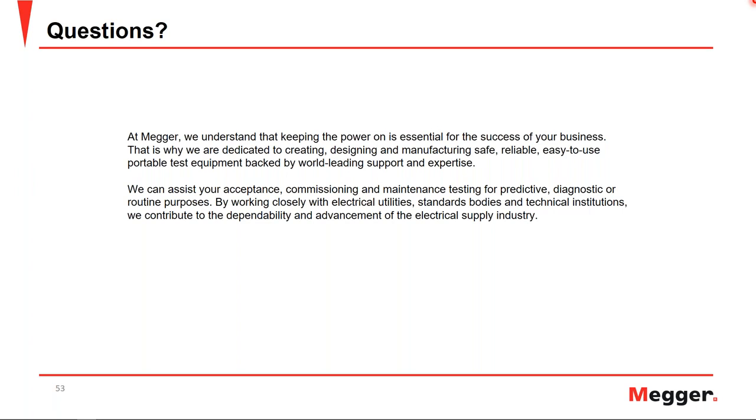Usually, I've seen utilities that do testing every 2 years. Other utilities do testing every 5 years. It also depends on what the testing practices are. Any data that you collect on insulation power factor will be beneficial for the future. You can trend values, you can collect data and see if there's any deterioration. So you don't have to do it every year.